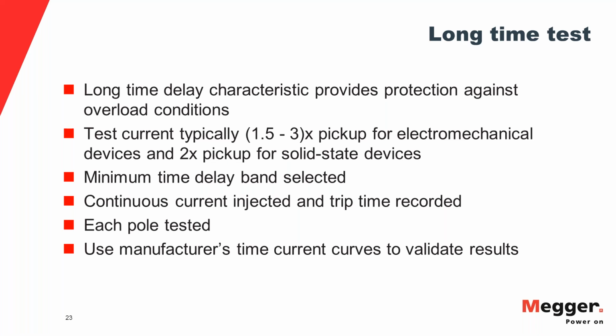the pickup level. The pickup level for the long time test is set pretty close to the rating of the overcurrent device. So the test current is set at 1.5 to 3 times the pickup for electromechanical devices, twice the pickup for solid state devices. The minimum time delay band is selected.